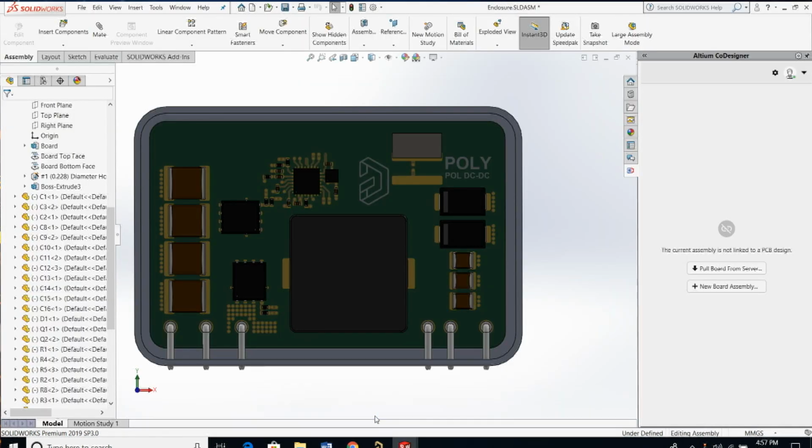So what you'll notice, and we'll talk about this a little bit more, you see that I moved the component, but the copper pad stayed behind, right? So right now, the way I have it set up, the copper is just a decal. It's essentially just a picture. So there's no real intelligence to it right now. So if and when we do a push and pull back into the mechanical realm, that copper will be updated, but we will see the component right now that's going to be moved in ECAD.